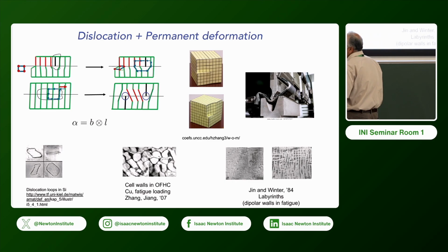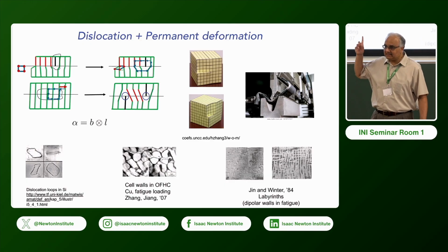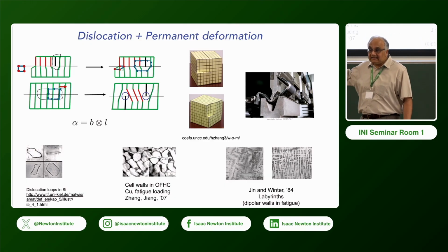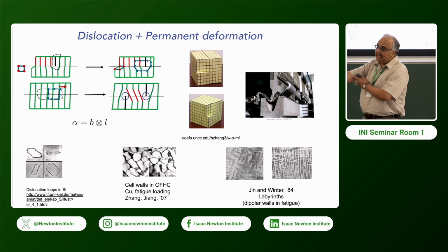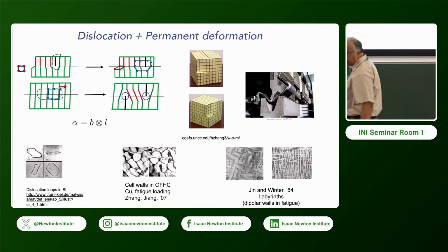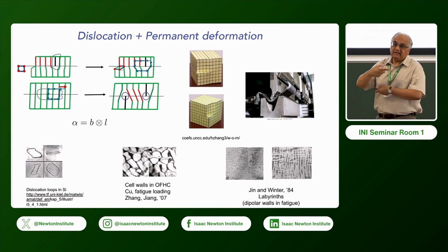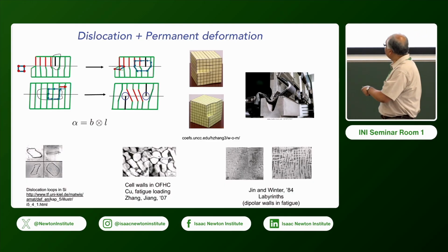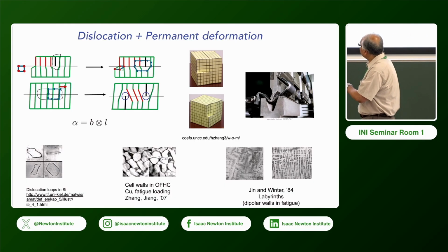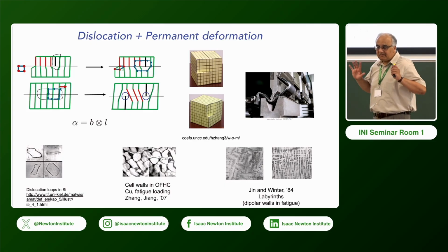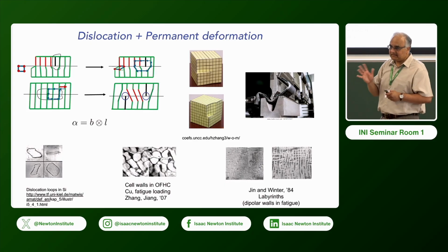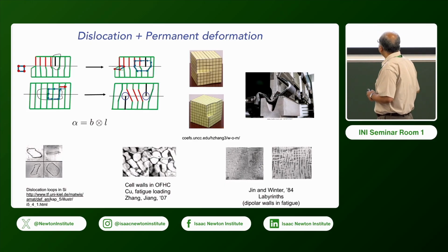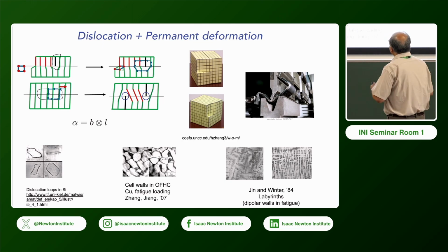And this is called the Burgers vector of this dislocation. And this dislocation is particularly called an edge dislocation. An edge is where the line through the plane of the paper is perpendicular to the Burgers vector. Okay, defined this way. In the undeformed lattice, the vector direction also is completely no problem. There is no deformation there. So you can pick this up. And okay, so that's the beast.